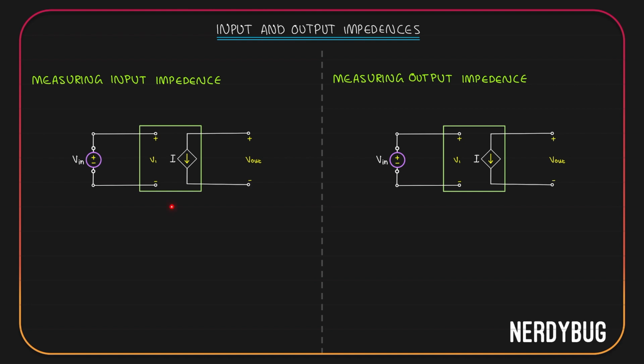For that, I have taken the basic idea of an amplifier that we developed before. The idea is this: we need a current source that provides a current I which will be proportional to the voltage that we apply over here. I here will be a constant multiplied by V1, V1 being the voltage that we give over here. So the first question is answered. We do have a dependent source in this, so we have to apply the second method.